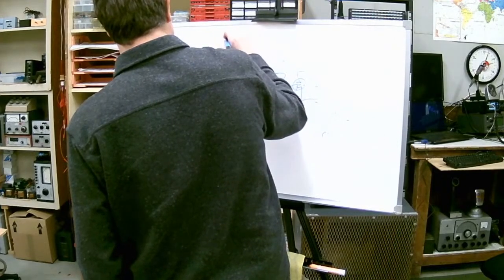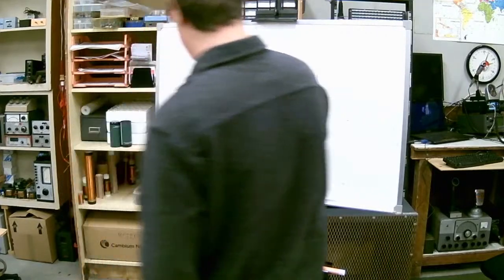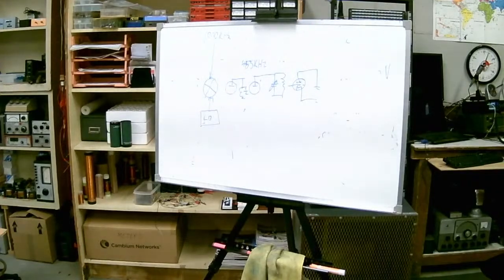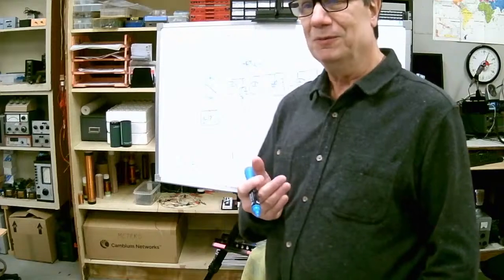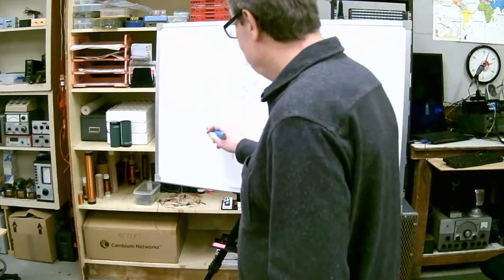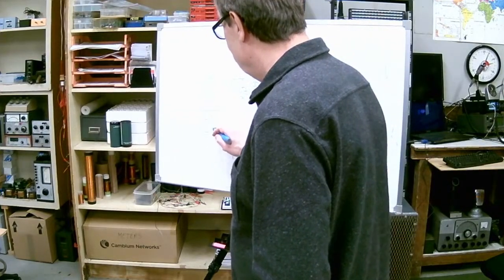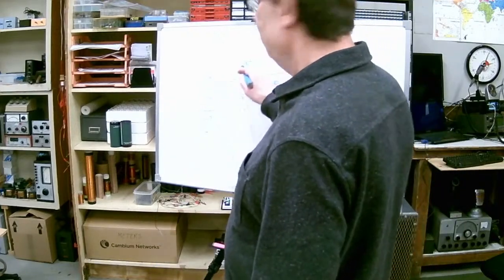We mix that, and any nonlinear device, including just a simple diode, will take any 2 frequencies put in it and give you the sums and the differences out. So we tune the local oscillator to 1455, which is the sum of these 2 frequencies. Take the difference out, which was 455 kilohertz.